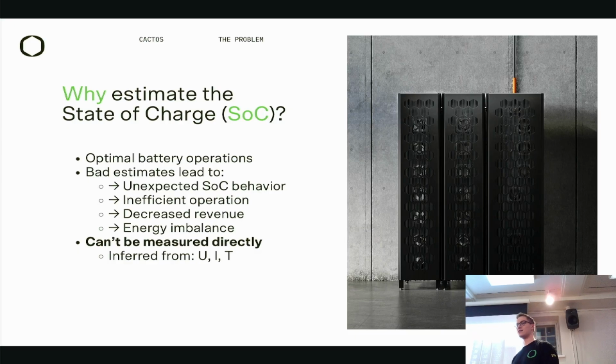The thing is, SOC can't be measured directly. It has to be inferred from operational and environmental parameters, such as voltage, current, and temperature. And in order to use these, a battery model is needed.